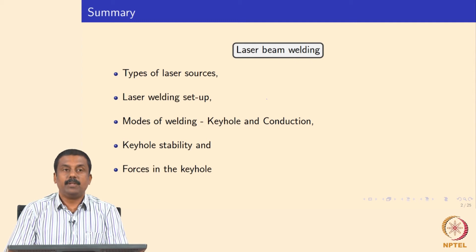So in order to improve the transfer characteristic to our benefit, as well as to reduce the heat input, we modified GMAW, gas metal arc welding. These modified GMAWs are sometimes used in the automotive industry to weld thicker sections, for example thick section advanced high strength steels or high strength steels, or in some applications where the weld strength is not really significant.